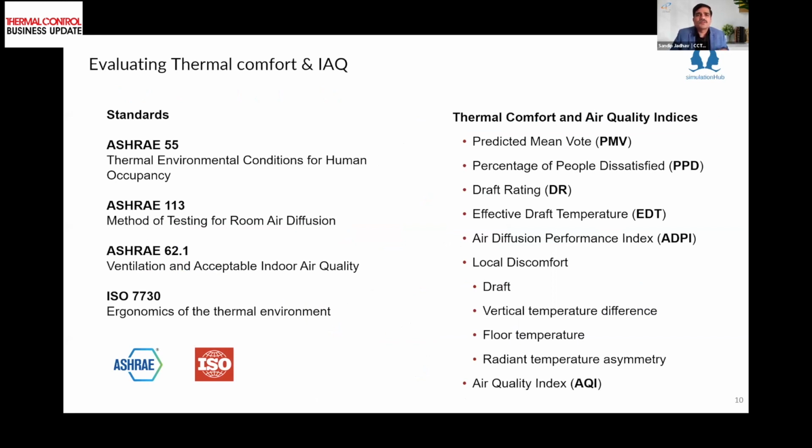ASHRAE 55 gives you a good guideline about what sort of PMV value you should maintain, what sort of PPD you should maintain. There are a lot of thermal indices available for someone to evaluate, but these are the most important, and ASHRAE 55 talks about two important ones. One is the PMV value, which uses all these four parameters and tells you whether you are going to feel cold, hot, slightly cold, or slightly hot.